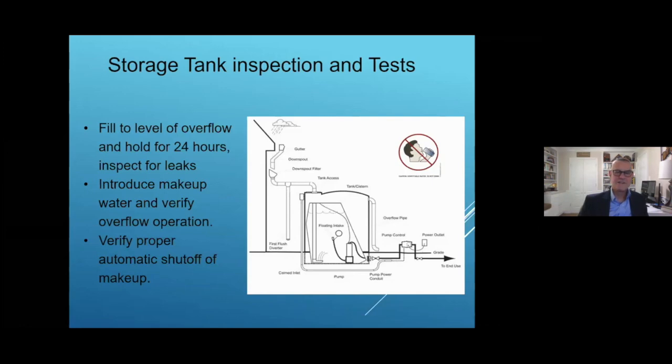And then if you have that, you're going to have to show that your tank holds water for 24 hours with no leaks. Then you have to drain it down in front of the code official, or verify to the code official that it was able to drain down. And when it got to the bottom, it has to show that the makeup water system turns on and starts filling the system and supplies it as intended. And then once it's filled to a certain capacity, it's got to show that it shuts off, right?